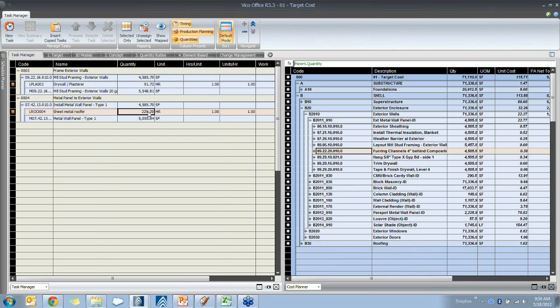What we are doing is assuming that the estimating hours that have been put in the estimate are correct, but we do have the opportunity to change that from a scheduling point of view and make our own assumptions, or we can ignore the resource level completely and add our own productivity rates in these two columns to calculate the amount of work that we're going to then schedule.